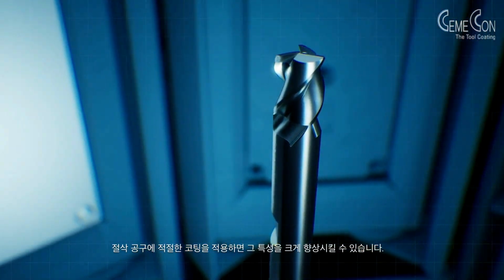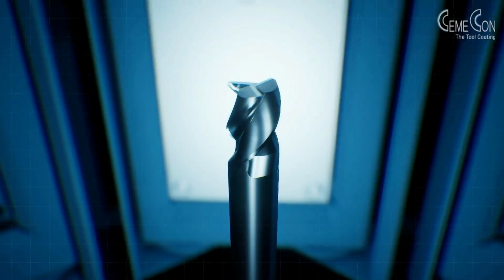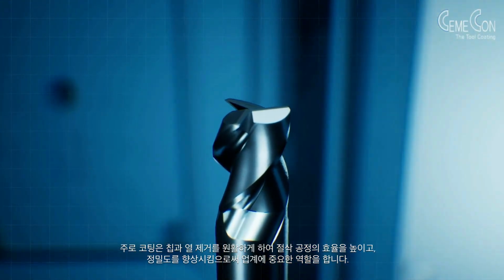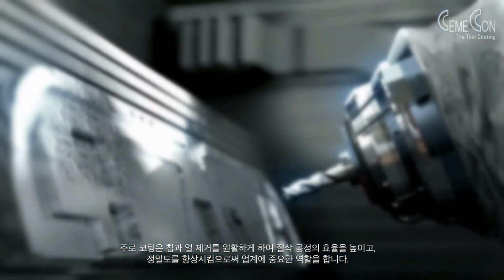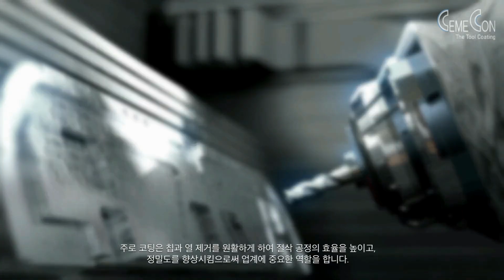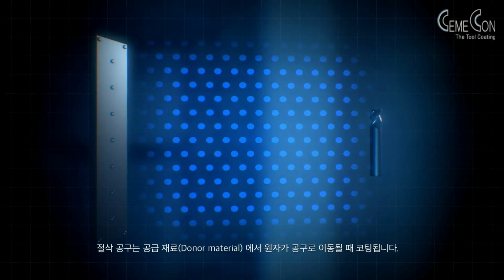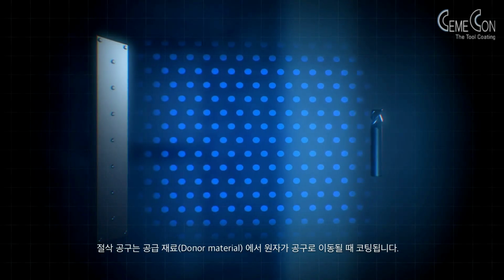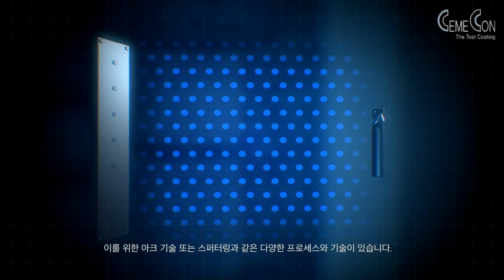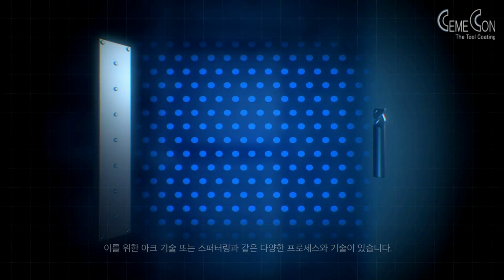The properties of cutting tools can be significantly improved by applying appropriate coatings. Primarily, the coating increases the efficiency of the cutting process by facilitating both chip and heat removal and improving precision, important factors for the industry. The cutting tool is coated when atoms are transferred from a donor material to the tool. There are various processes and technologies for this, such as arc technology or sputtering.